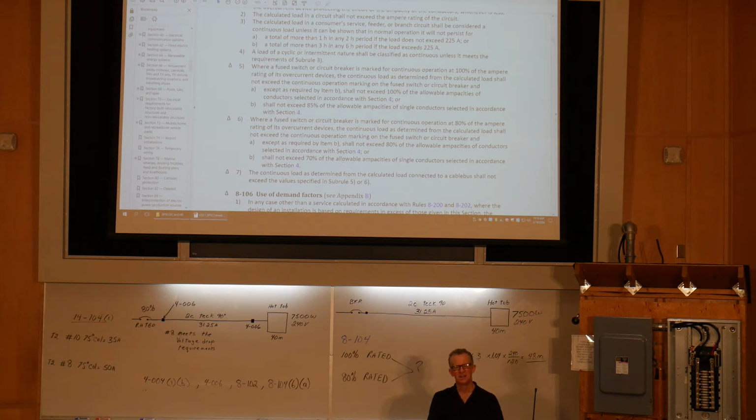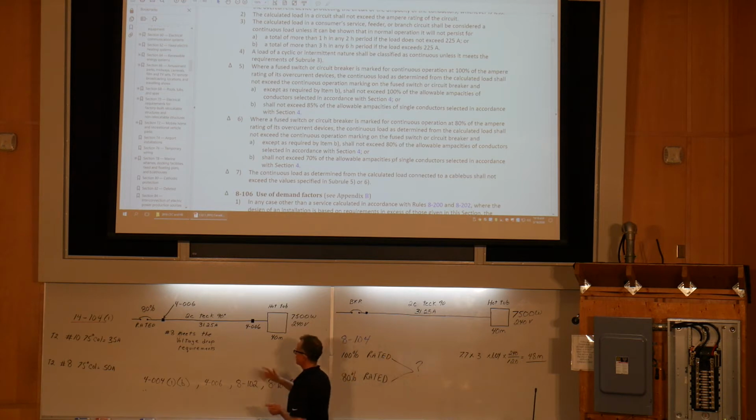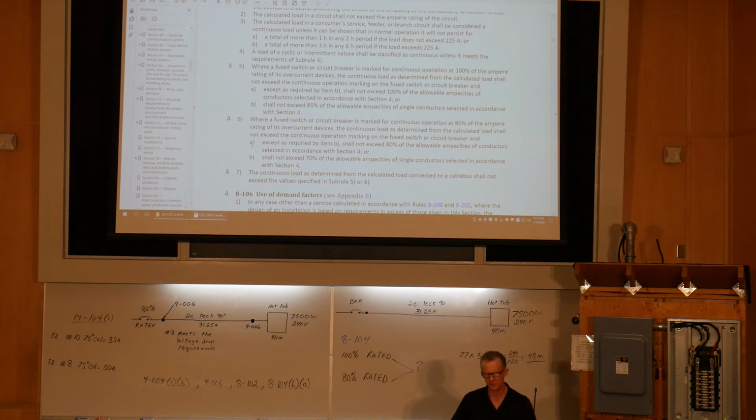So, single conductor cable, if we were using the single conductor installation method, which we're not, here we're running a 2-conductor tech cable, so B does not apply. So we're going to be using A. So here, students, what we need to know is in table A, which tables apply, and we're using B, which tables apply. And it applies to both subrule 5 and 6.